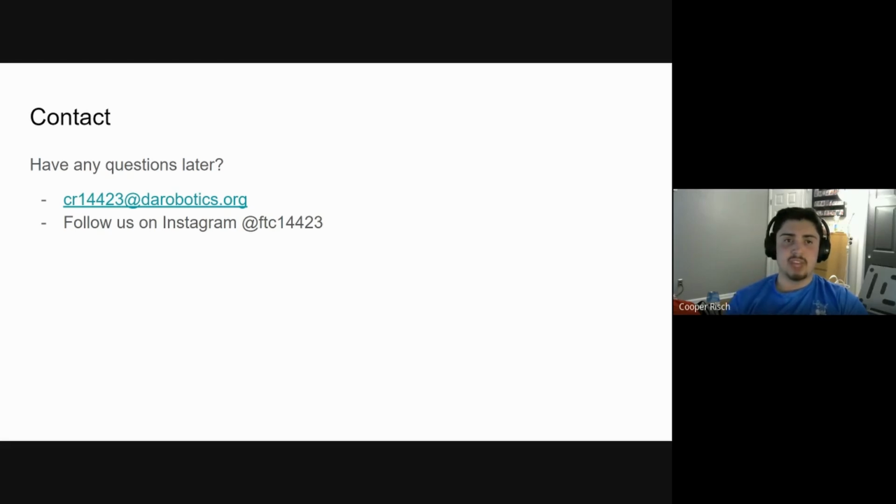And so in using nTop, they have integrations with Fusion 360. If you know how to use Fusion 360 really well, Fusion can actually open implicit files. So if you design something in nTop, you could open it in Fusion and use their additive manufacturing capabilities. But if you're not good with Fusion, like I'm not, what I did was use Bambu Studio to 3D print. I would just import the shell and the optimized region, because I can mesh that with triangles and not crash my computer. For the lattice, I just imported the region that it had, and it can mesh the region. So it's not the actual lattice itself, it's just the space that it fills. I can import that into Bambu Studio, and then you can make that into the lattice. And so that's how I solved the problem. It is definitely an issue. Sometimes it's hard to make these parts.